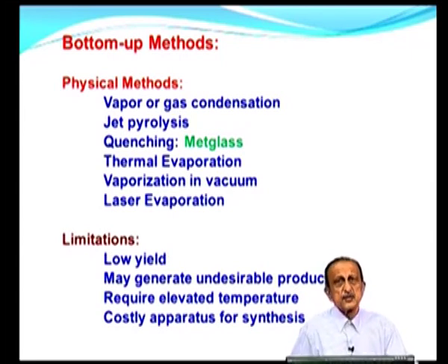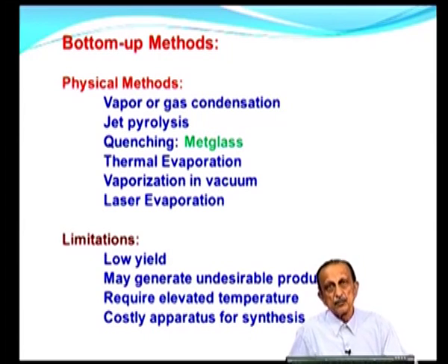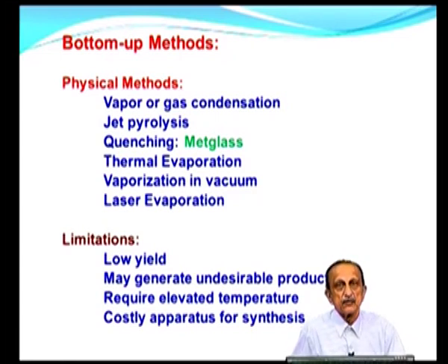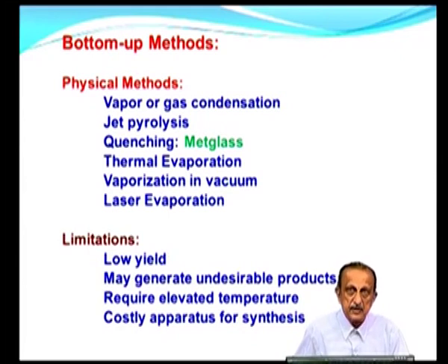Jet pyrolysis is really much the same. You have a jet of particles moving at a high speed, which means high kinetic energy and high temperature, and then you suddenly cool it to obtain a condensate that would contain nanocrystals or even amorphous materials, as I just mentioned.